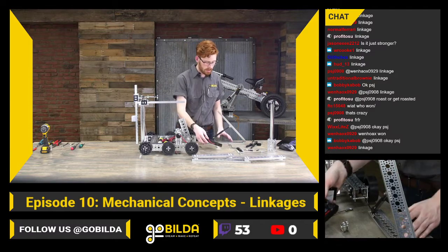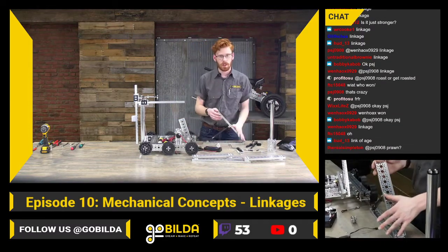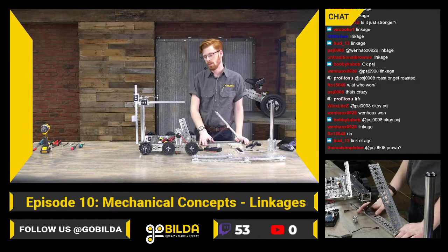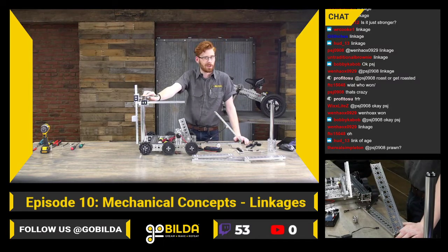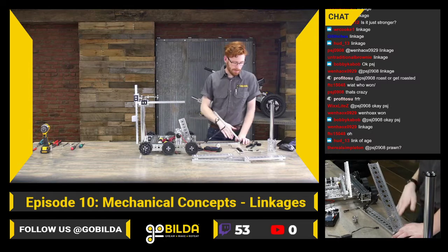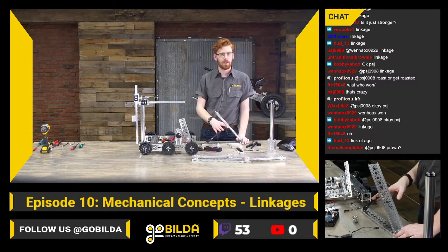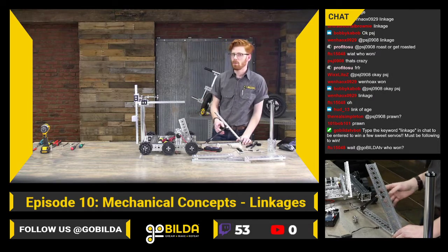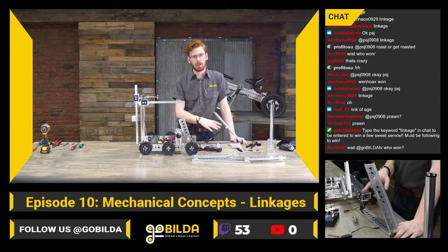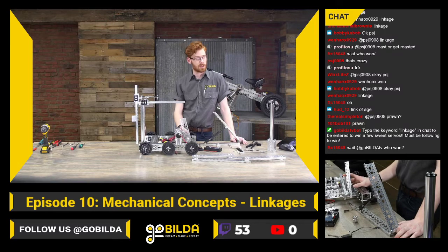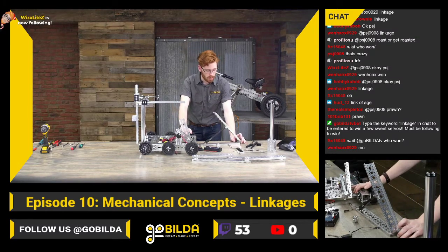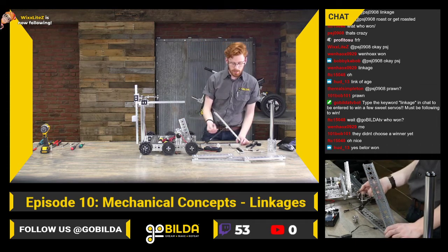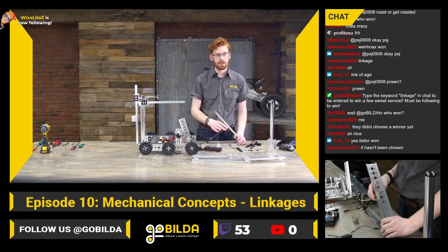With this, your amount of torque that you get out of it is effectively the same way you would figure out how much torque you get out of a servo, but backwards. If you have, in this case, a 6-inch lever arm, and you're putting 1 pound of force on this, instead of having 1/6 of an inch-pound like you would if you were powering the rotation, you're going to get 6 inch-pounds because you're putting that 1 pound 6 inches out.